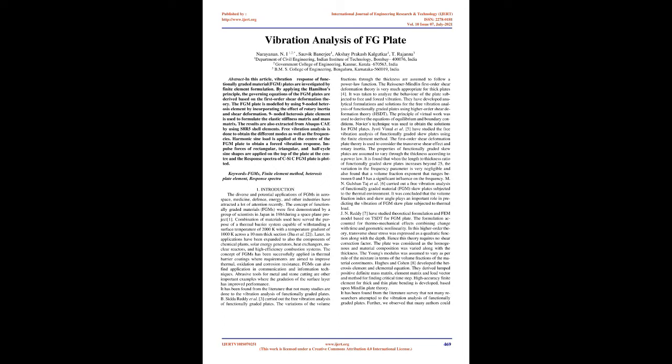By applying the Hamilton's principle, the governing equations of the FGM plates are derived based on the first-order shear deformation theory. The FGM plate is modeled by using 9-noded heterosis element by incorporating the effect of rotary inertia and shear deformation. The 9-noded heterosis plate element is used to formulate the elastic stiffness matrix and mass matrix.